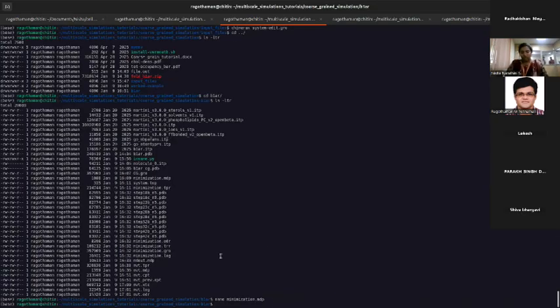So when you run the energy minimization, I'll show you the command to run the energy minimization step. So here, you have to use grompp in order to generate a TPR file, which basically collects all the parameters that you have given and also combines the input data.